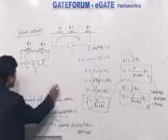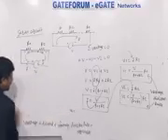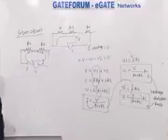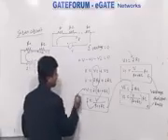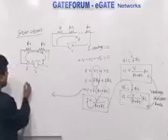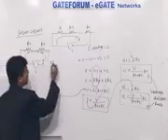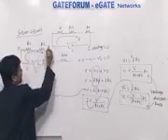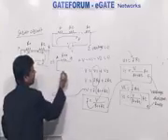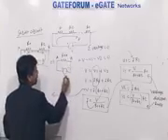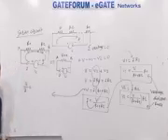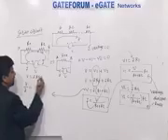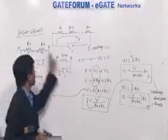Now in similar way, I can say that whatever equivalent resistance is there, I know that. Now if multiple resistors are connected in series, from this expression, I can say V upon I. Suppose I want to reduce this circuit into the equivalent resistance circuit between A point and B point. Voltage is applied as V. This is current I. So I can say that V is equal to I into R equivalent, because R equivalent is nothing but equivalent resistance of this series combination.